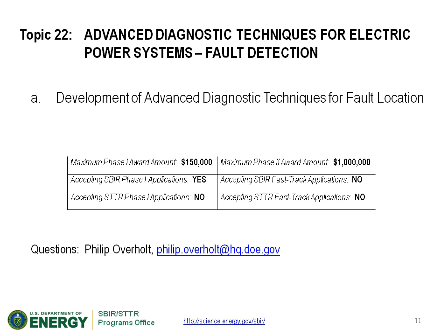So what we're looking for here, and also these types of partial discharge faults are what you're looking for with that technology. For essentially a fault where the circuit's tripped, you really can't apply that technology because if there's a flashover, then it's there and gone.